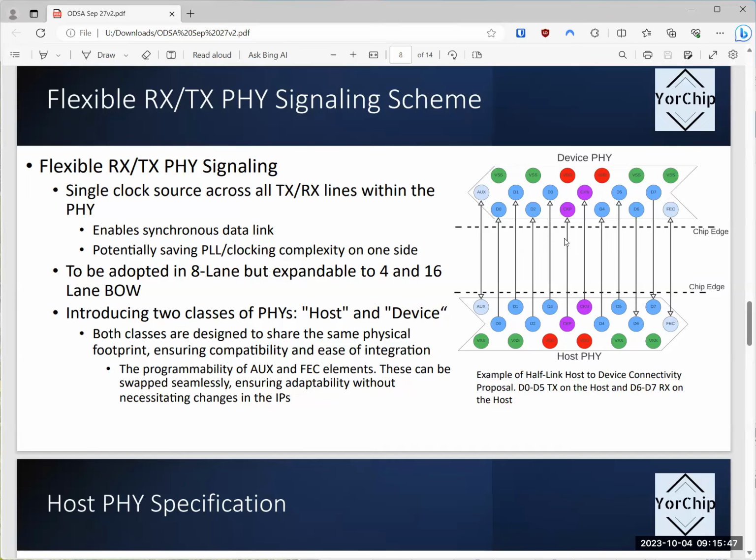Yeah, but the first reason we use those for bits is cost, right? Cost is area. Then all that redundancy and so on will defeat the purpose, right? This one also removes the clock on the RX side, meaning the PLL. So if I build the PHY as a bundle instead of single bits with the PLL and bundles, then I don't have the area saving either, right?